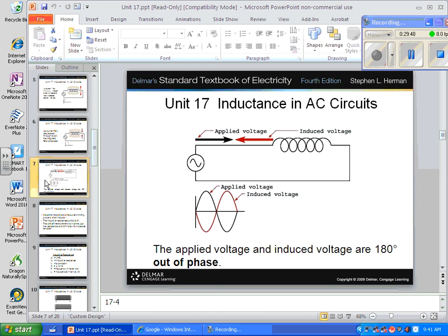So we've talked about in first semester that you have pure resistance, and I call it pure DC resistance, right? The wire has a resistance to the flow of AC or DC, and I call that pure DC resistance. But when you have a winding, it has inductance, which is a resistance to flow of AC through the winding. Because of that, you're going to have less current flow because of this counter EMF. And the total of pure resistance and pure inductive reactance is called impedance. The total resistance to AC flow is called impedance.